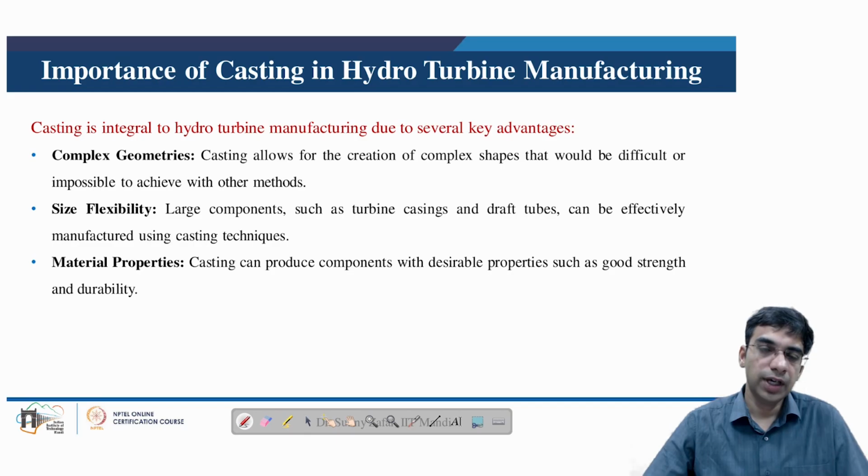The shape of the mold cavity is basically created using a pattern, which is a replica of the product to be produced. Subsequently the solidification of the molten material takes place in the mold cavity, and upon completion of solidification the solidified part is removed from the mold. Casting, as we know, has special abilities, with controlled parameters, to generate complex geometries.